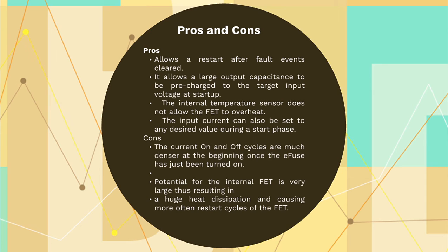Cons. The current on and off cycles are much denser at the beginning once the eFuse has just been turned on. The potential for the internal FET is very large, thus resulting in higher heat dissipation and causing more frequent restart cycles of the FET.